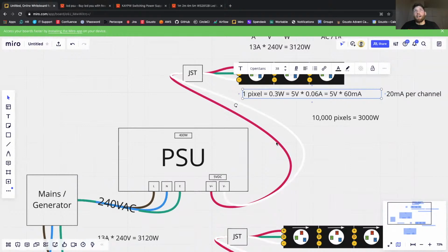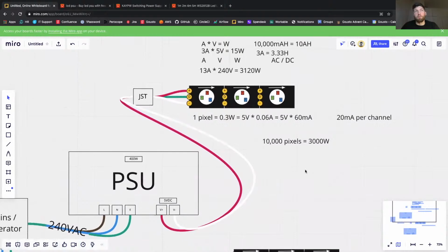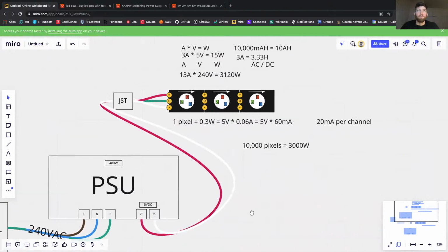And this line carrying power from your PSU to your LEDs, to your load, as short as possible. Because 240 volts is less susceptible to voltage drop. And the appliances 240 volts typically run are less vulnerable to lower voltages than these low power or low voltage circuits.